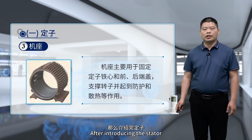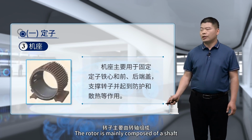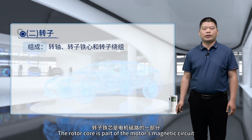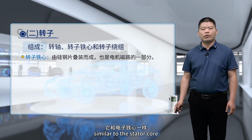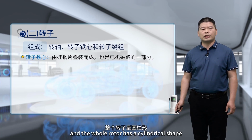After introducing the stator, let's take a look at the motor rotor. The rotor is mainly composed of a shaft, rotor core, rotor winding, and other components. The rotor core is part of the motor's magnetic circuit. It is also made of 0.5 mm thick silicon steel sheets, similar to the stator core. The rotor core is fixed on the shaft or rotor support, and the whole rotor has a cylindrical shape.